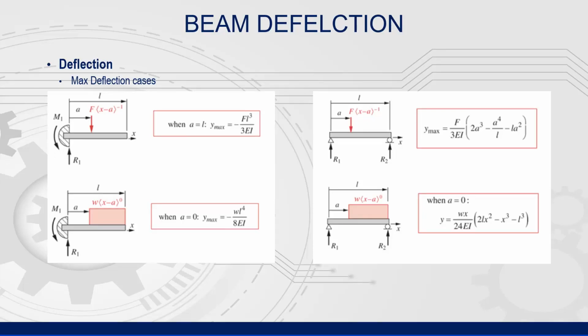While deflection and stress are related, for determining design safety, we are usually more interested in stress. Deflection becomes a point of interest when we need to confirm that the loaded system will not create an interference or otherwise violate some stated code.